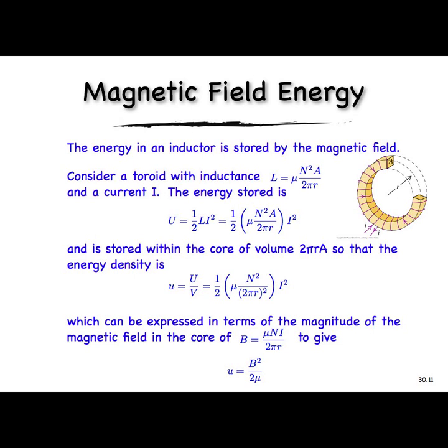So L is a constant. It comes outside the integral, and I'm left with the integral of i. So I get i squared, take the power there and put it in the denominator. I'm left with 1/2 L i squared. And I evaluate that at this limit, I get this. I evaluate it at this limit, and I get 0. Okay, so the energy starts at 0 and ends up with 1/2 L i squared. So this is how much energy is stored in the inductor.